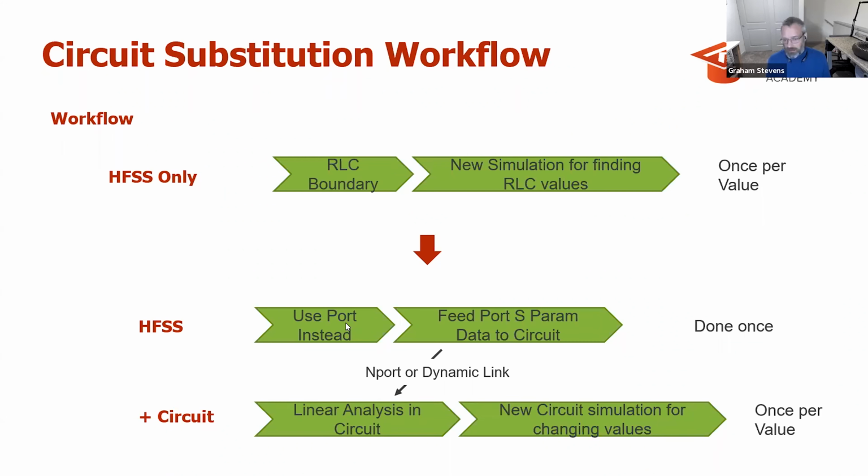And then take the resulting model results and feed the port S parameter data to an equivalent circuit, which I'll discuss or just demonstrate in a few minutes, using an import or the dynamic link feature of HFSS, and then do a linear analysis in circuit where the R, L, and C values are within the circuit and changeable within circuit.